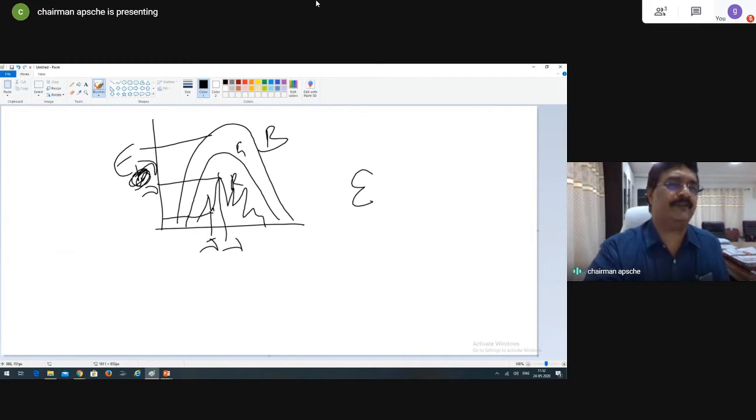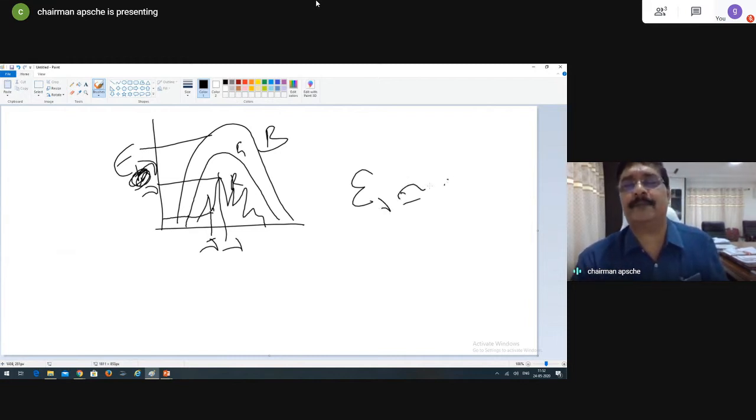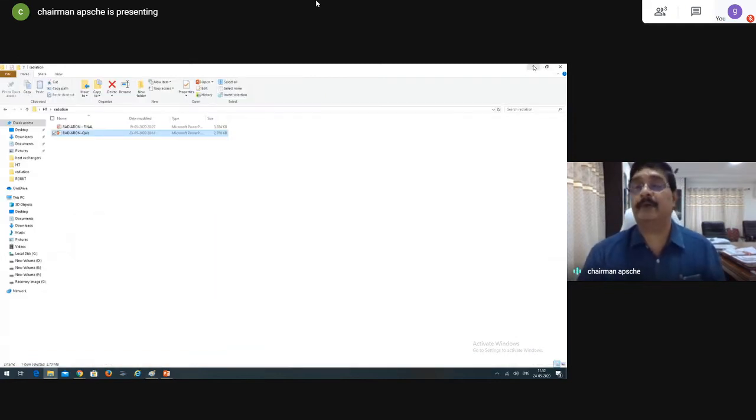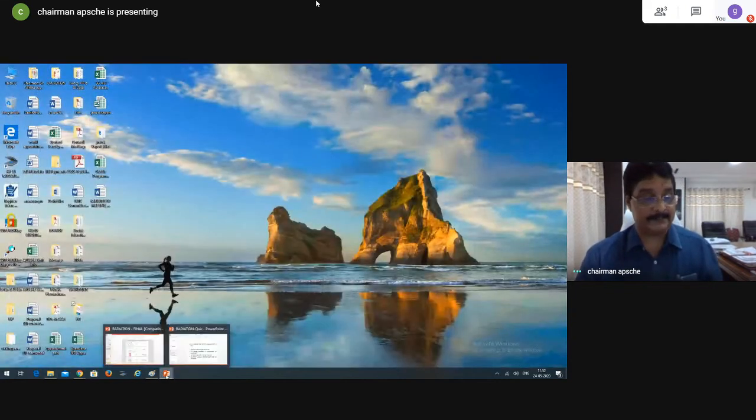So the ratio between these two curves will always be approximately constant, not really varying, for a gray body. That is the difference between a real surface, a black body, and a gray surface.